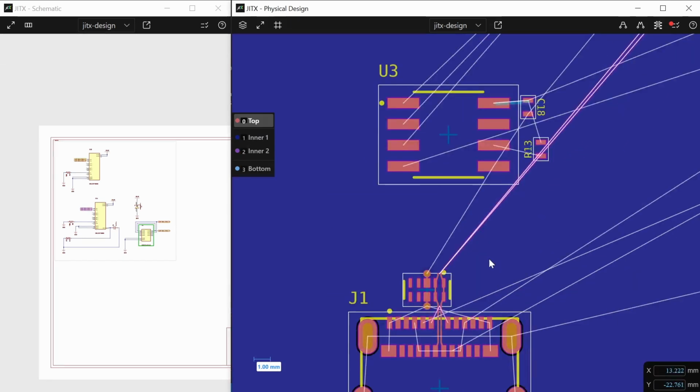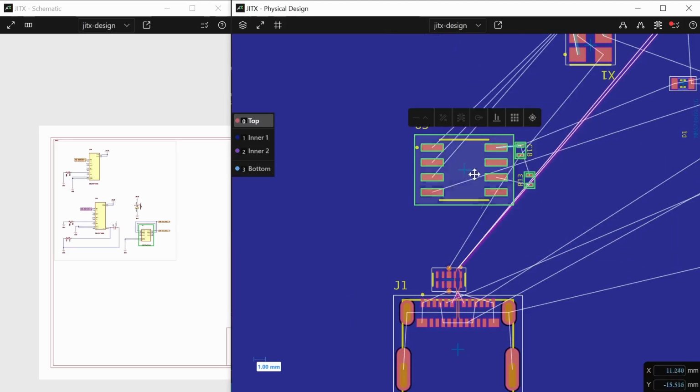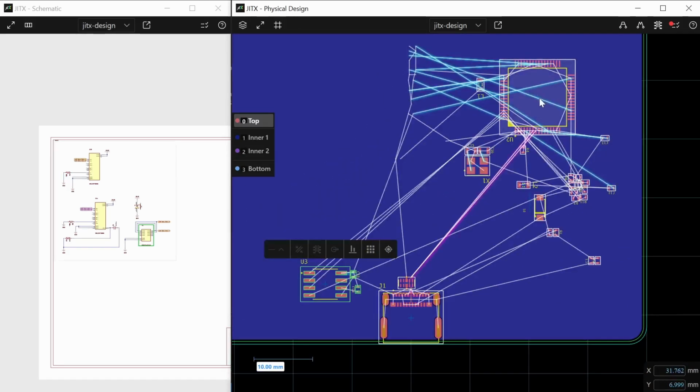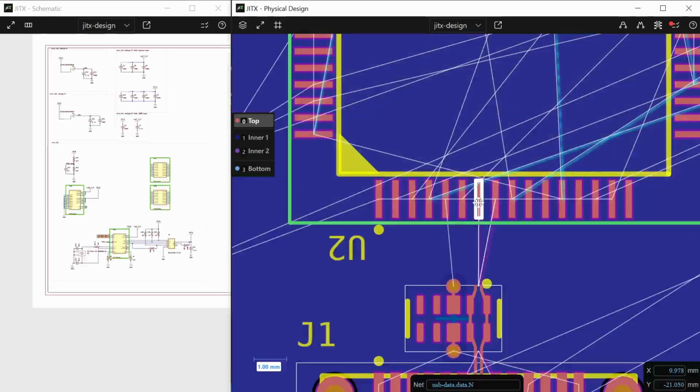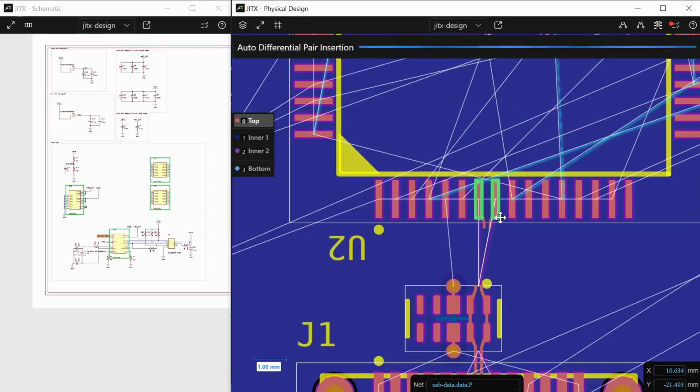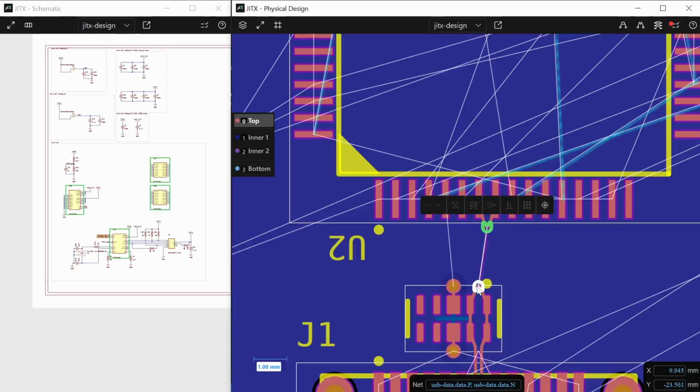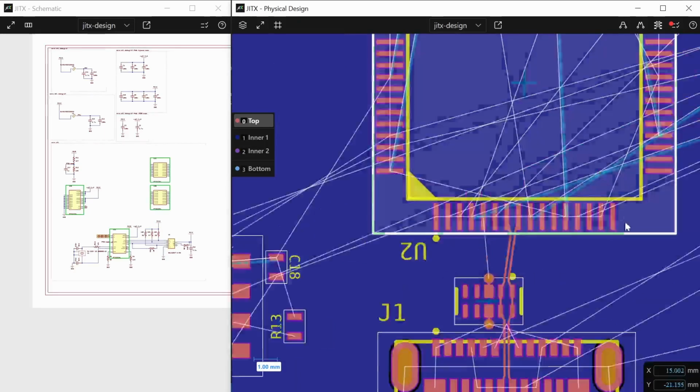You can also control the direct path of a route, so let's move our EEPROM out of the way, and we'll bring our FTDI chip down here. Again, Shift I, insertion point, select and press Q to auto route.